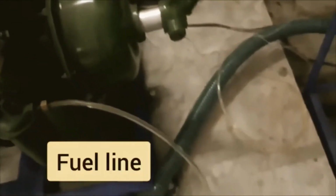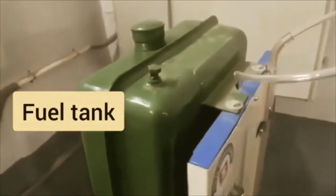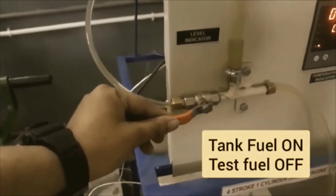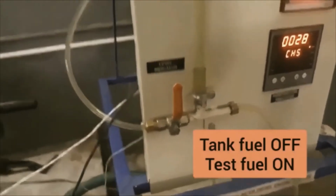The fuel line connects the engine to the burette and the burette to the fuel tank, which supplies the diesel. For measuring the fuel consumption, here we open and close the valve for measuring the diesel consumption.